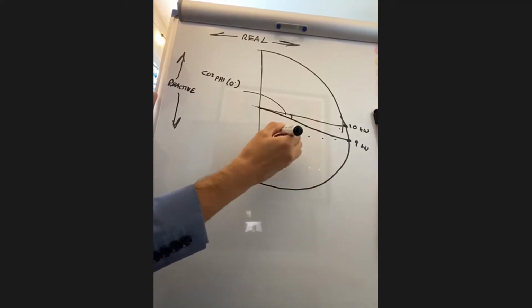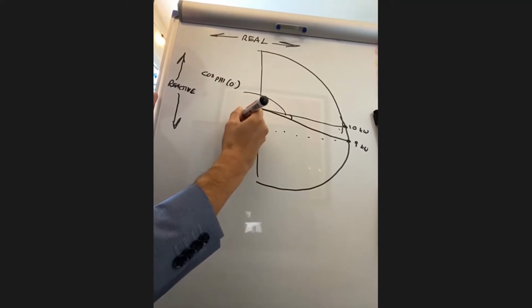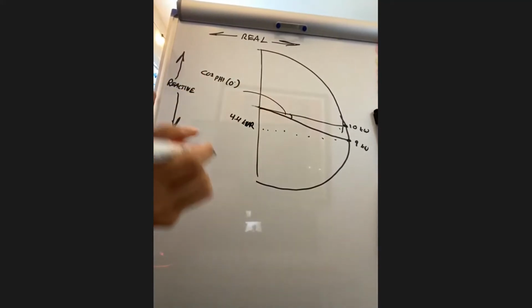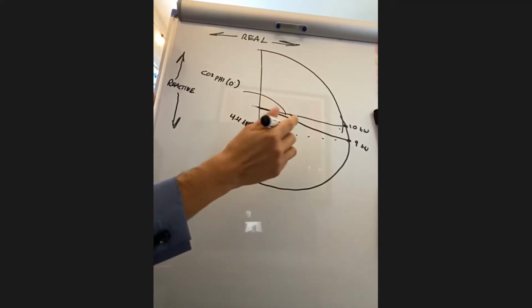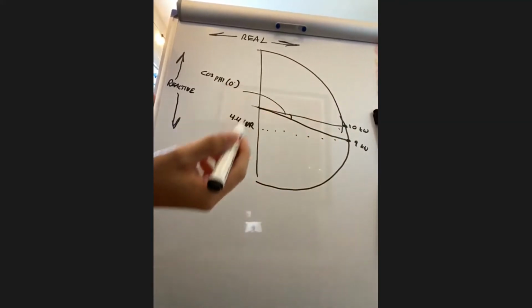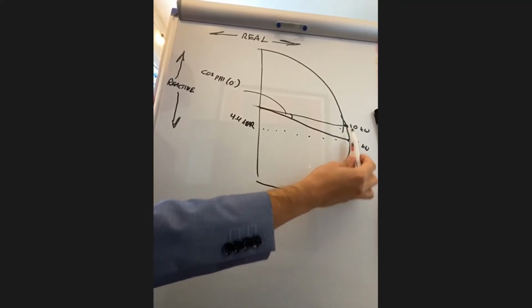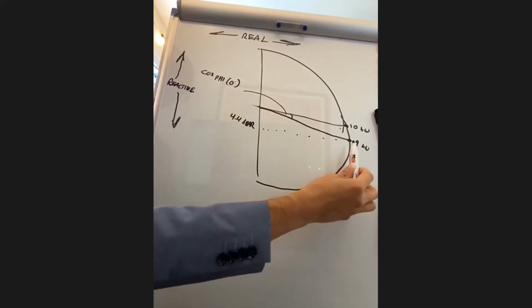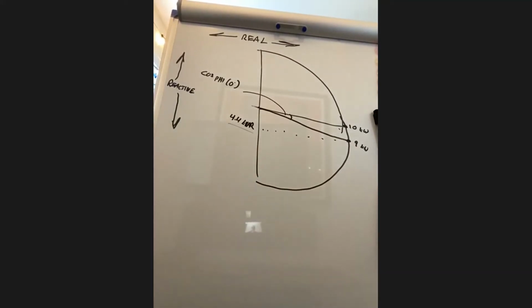However, if you bring it out to here on this axis, you end up producing 4.4 kVAR. So essentially, it's just trigonometry. You can figure it out with this angle and the Pythagorean theorem and whatever equations like that. But by sacrificing 10% of your real power production capability for a voltage support function, you gain 44% of reactive power capability there. And so I think that that's really profound.